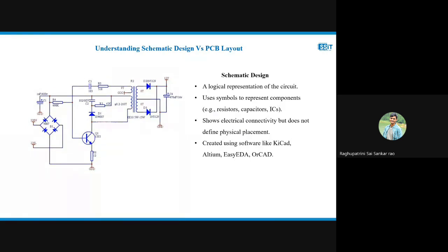Anything can be worked with, but one thing to note: whenever we are designing the schematic, the same software should be used for the PCB layout design also. We cannot use the schematic in one software and the layout in another. If we want to do it that way, we have to migrate the schematic from one software to another. For example, if I had a design and schematic in Altium and want to design a layout in EasyEDA, we have to migrate the Altium design into EasyEDA, and then do the corresponding layout work.